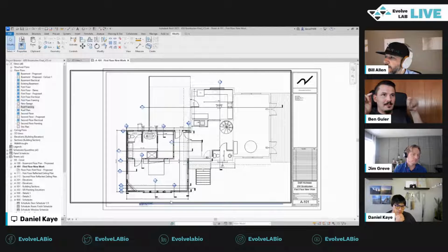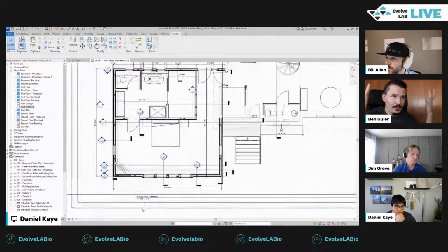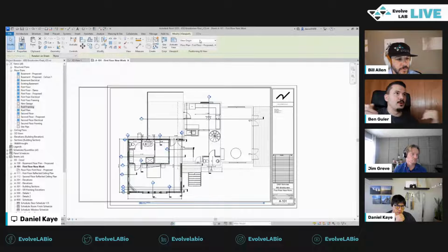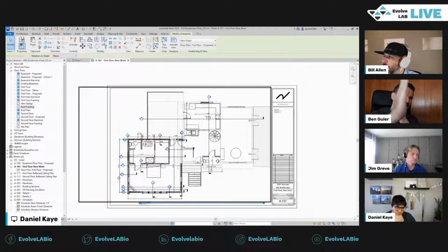You don't want to keep that same model origin across both of the sheets. So you can use either one, the view origin or the center one, depending on how you want to flex on your sheet. If you care about keeping the same wall across all the levels in the same spot, versus I want the view to flex around the sheet.